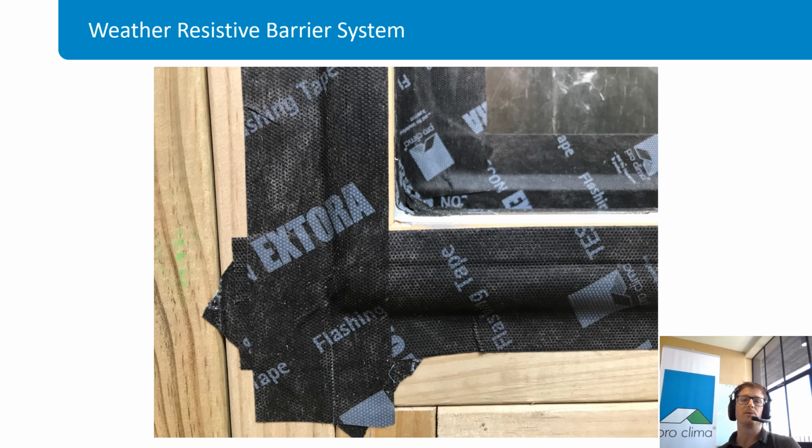Another way to address this is to use taping systems. Taping systems operate slightly differently because they are flexible. So that means if you've got wind pressure on the outside of the building, the tapes are able to flex under movement of the facade. But also as the building settles and as the building moves over time, those seals can maintain their integrity.